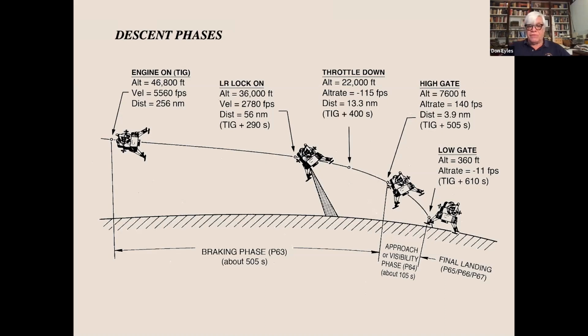The commander on the left did this, to see where the guidance thought it was taking the LM. And if they didn't like that spot, they could tweak the rotational hand controller that wasn't needed at that moment for anything else, to shift the landing site by a discrete amount, uprange, downrange, left or right.